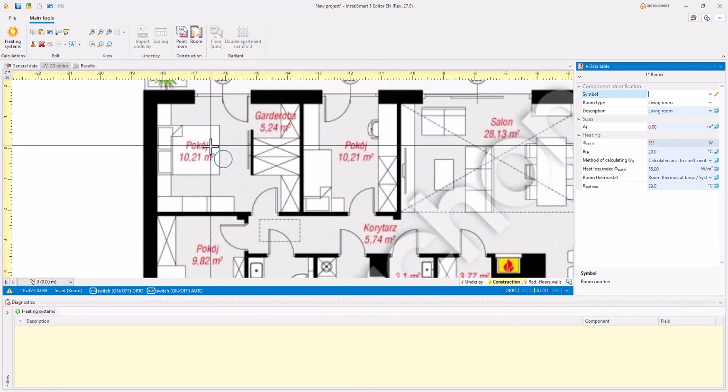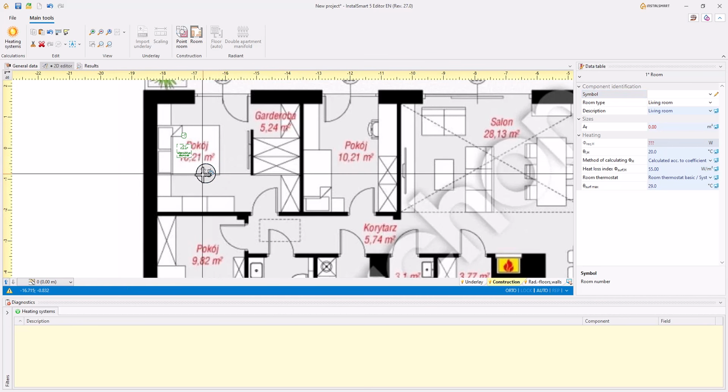In practice, the user simply inserts a label, which is placed along with the floor heating system. Labels are positioned approximately at the geometric center of the room. If you need to adjust its position, you can always grab and move it. To speed up the process, use the repeat mode.